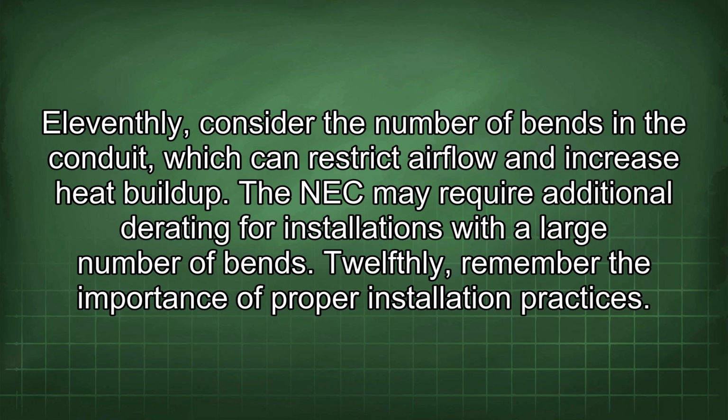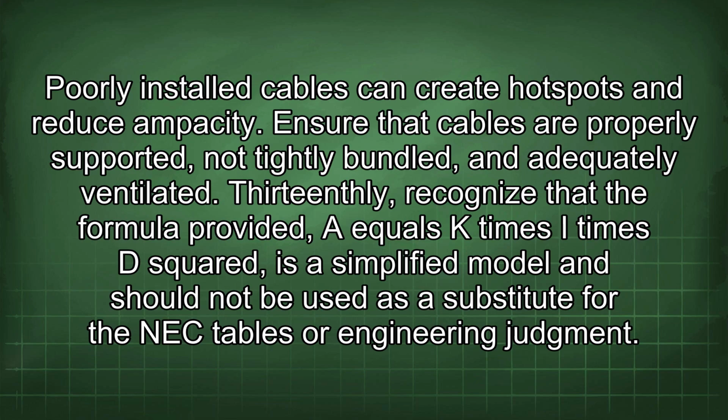12thly, remember the importance of proper installation practices. Poorly installed cables can create hotspots and reduce ampacity. Ensure that cables are properly supported, not tightly bundled, and adequately ventilated.